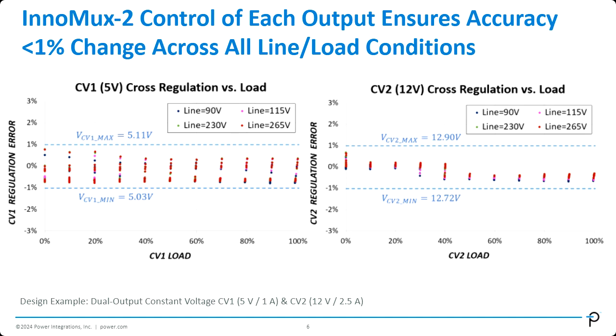And in terms of when we can use single winding designs, it really depends on the output voltages and the output voltage allocation. So for example, if we use a 5 volt, 12 volt, where the output voltages are not too far apart from each other, we're probably fine. Most likely we're fine with a single winding.